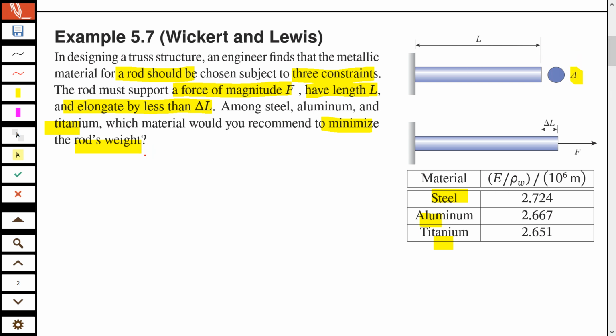Because you know that force divided by area will give me stress, and you already know that stress is what can cause failure. So, for example, stress must be less than the yield strength. So area is also important. If you want to minimize failure, you would go for more area. Why? Because F is fixed. So more area means that you will have more stress or less stress? Less stress. Less stress means that you will be away from failure, from the danger zone. So first we need to now work out the area.